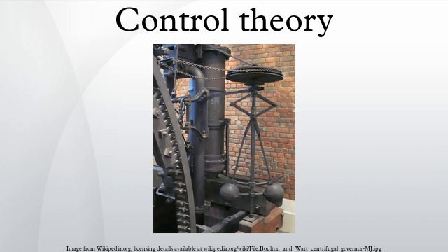PID controller. The PID controller is probably the most used feedback control design. PID is an acronym for proportional integral derivative, referring to the three terms operating on the error signal to produce a control signal. If u(t) is the control signal sent to the system, y(t) is the measured output and r(t) is the desired output, and e(t) is the tracking error, a PID controller has the general form.